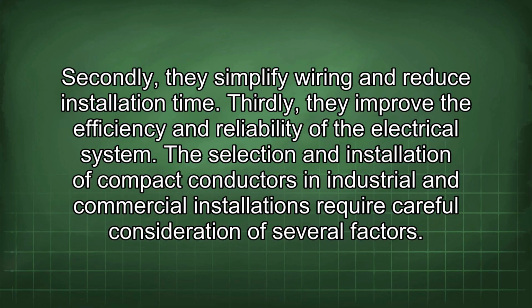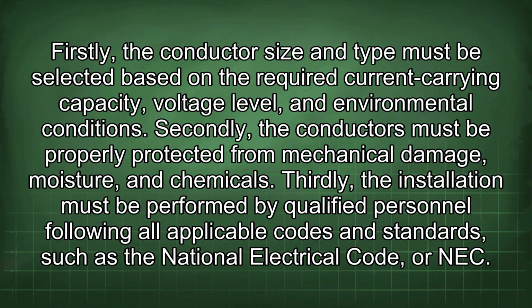The selection and installation of compact conductors in industrial and commercial installations require careful consideration of several factors. Firstly, the conductor size and type must be selected based on the required current carrying capacity, voltage level, and environmental conditions. Secondly, the conductors must be properly protected from mechanical damage, moisture, and chemicals.